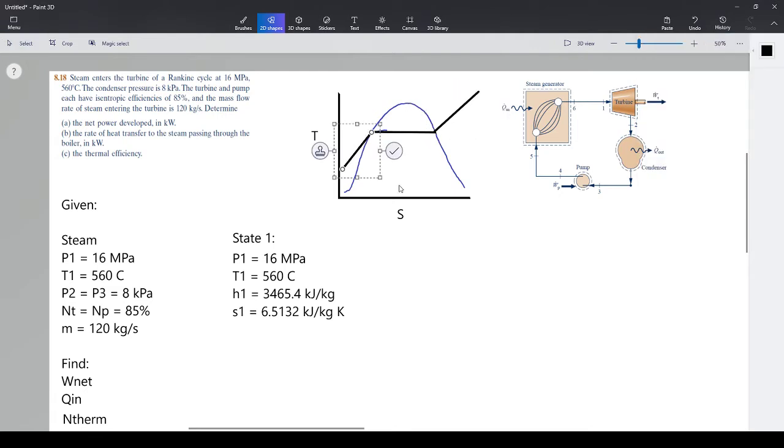So this right here is our pressure line. This is our first pressure, P1, but it's also pressure 4, because pressure 4 is on the same pressure line as state 1. So it's P1 or P4. I'm just going to draw us right here. Like I said, there's no way of really scaling this properly, but we are on that line right there, and this will be state 1. Pretty straightforward. We are in the superheated region, and I drew us on this line. It's kind of arbitrary, anywhere you draw it. But we are state 1 right there.